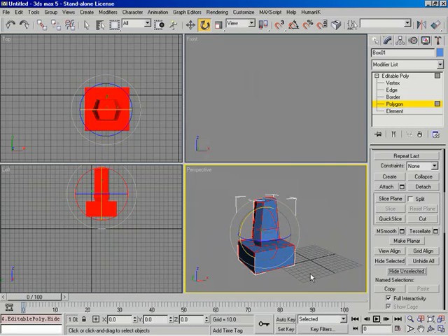This is very important. Like if you're working on the eye of a character and you've got a selection set made, you go in there and grab that selection set, say hide unselected, then you can focus on just that. Yeah, this could also be really handy if you've got a really heavy scene and you've got to just work on a certain part of it without slowing down your viewport. Absolutely. So you can keep your viewport fast, or you can also keep less clutter going on in the scene. Less visually confusing. Exactly.